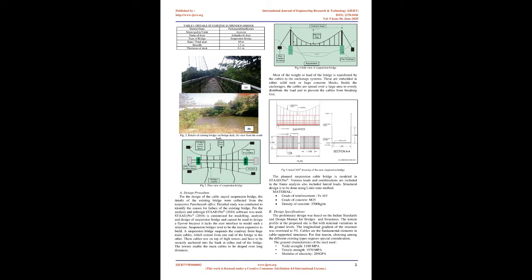The hangers are provided with steel pipes which are more suitable than steel ropes. A handrail is provided at a height of 1.5 m from the base plates. A number of steel base plates are used for the steel deck. A steel wire mesh is also provided for protection. Details of the existing bridge are given in Table 1.